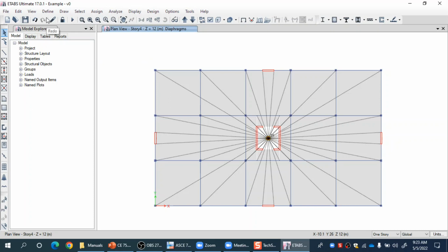So this is something which you have to first do even before starting to make the wind load pattern. Define the diaphragm and then assign it to your floors. It can be rigid or it can be semi-rigid also. The program will apply one force value at each floor if you go for the rigid option, and it will distribute that force into different elements in the horizontal direction for each floor if you go for the semi-rigid option. So this is the point I wanted to make here